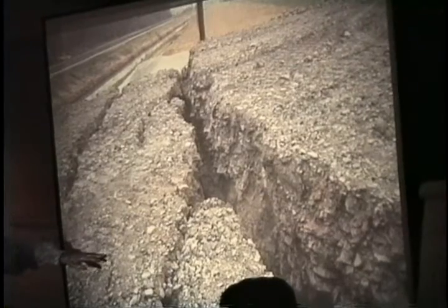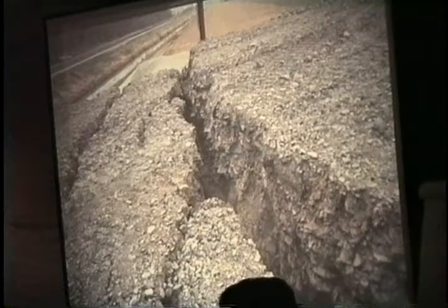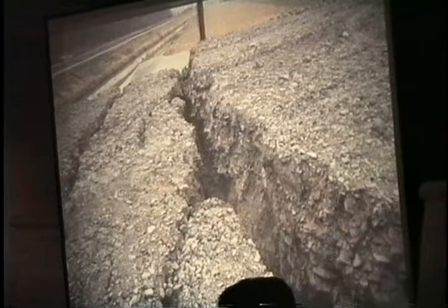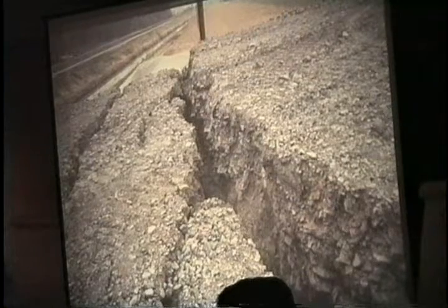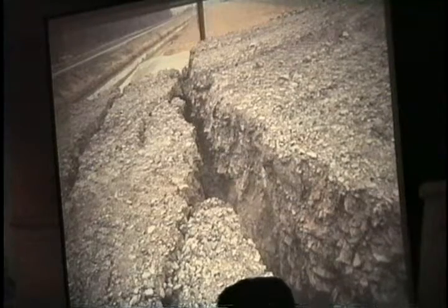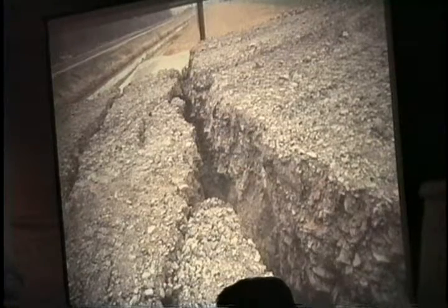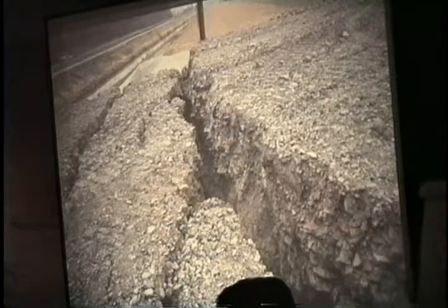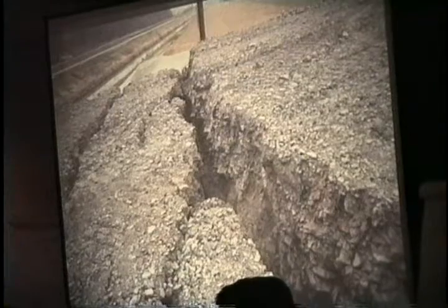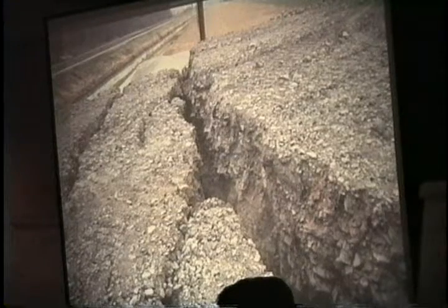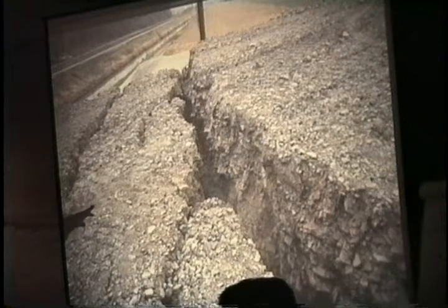Eight feet below the bottom of the embankment was a thin layer. I mean thin. And it was CH material, which is highly plastic clay. And it had a strength of 80 pounds per square foot. For shear strength of soils, that is unbelievably low. Okay? I mean, you would want like 600 as a minimum for that thing to work.